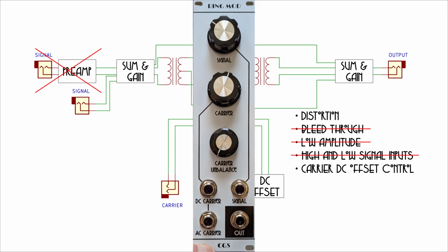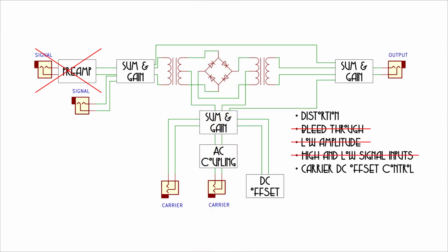And then finally, I switched out the transformers. The ones Stone recommended are a little bit harder to acquire, and I decided to use a couple of different transformers that I was more easily able to obtain. They have a different footprint than the transformers that Stone specified, so I wasn't able to use the commercially available circuit board. I just designed my own circuit board and built the Kosmo format ring modulator. Let's take a look at it.